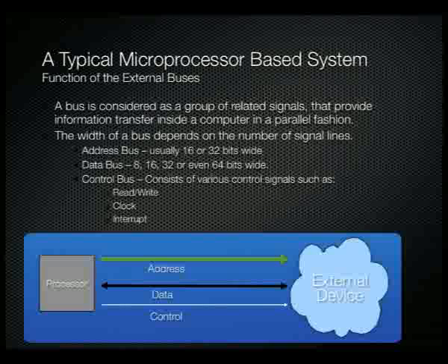The address bus is responsible for transmitting addresses outside of the microprocessor. Those addresses that come out of the microprocessor are basically responsible for turning on a particular device that is memory mapped into our memory. It may be to turn on a particular memory element in our RAM, or maybe a particular I/O device or whatever. But basically it contains the addresses to turn on particular elements in our memory map. The address bus can be 16 or 32 bits wide, depending on the kind of processor that you have.